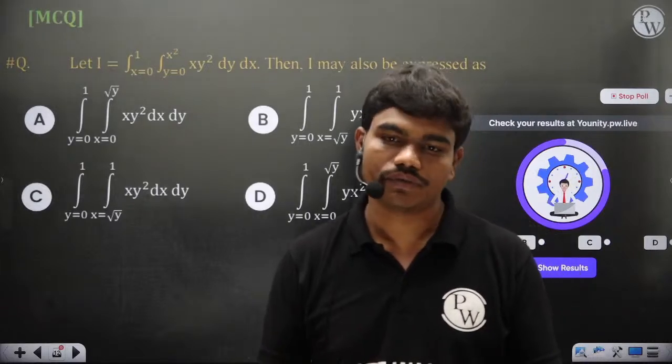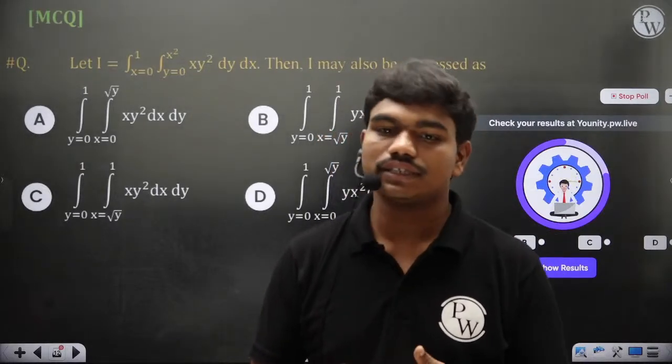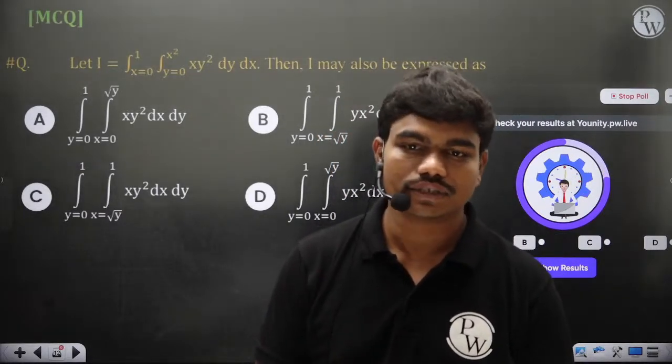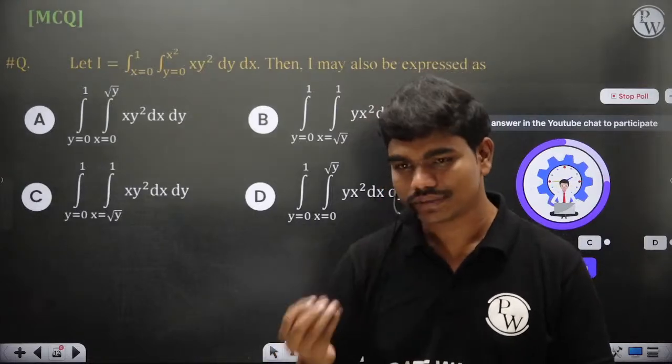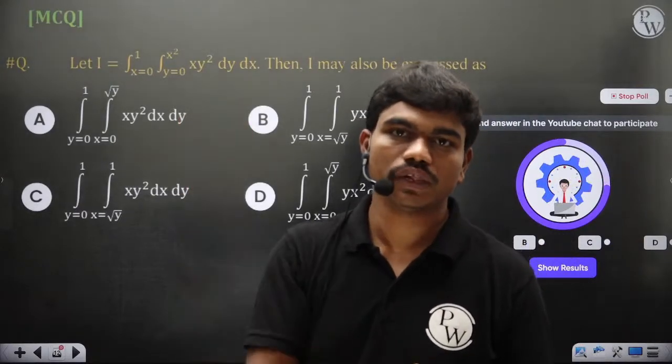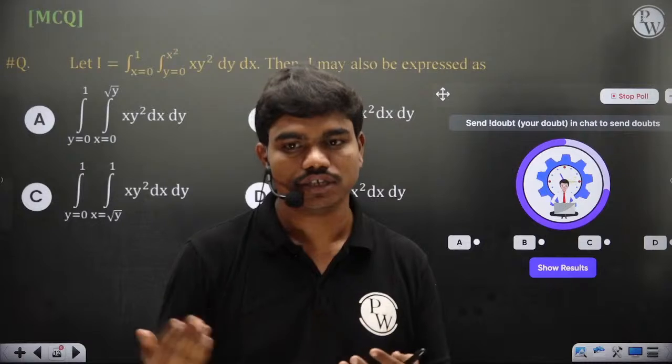Sir, do we have intercooling in Brayton cycle? Intercooling is a very small concept. If you want, you can study it now. Let's take the safe side and say it is there in the syllabus, because intercooling is a very easy topic. You just cool the air in between the compressors, in between the stages, to reduce the work input.